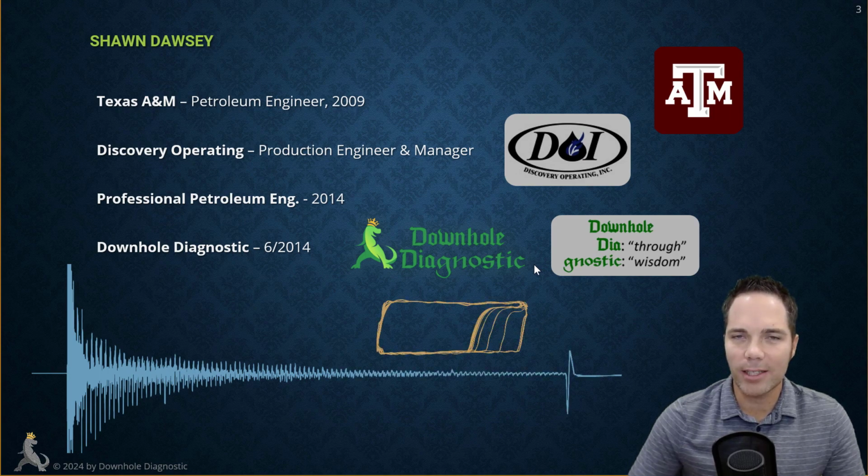We have two diagnostic tools. We have the fluid level gun that is looking down the annulus. We can see where the top of the fluid level is, if there's additional production potential, also what our bottom hole pressures are. And then our dynamometer test is looking down the rod string, and based on the shape of the downhole pump card and how the fluid load is picked up at the start of the upstroke and how the fluid load is released, we can determine what condition the pump is in, but also what condition it is operating in. And this would indicate right here that we have fluid pound due to incomplete liquid fillage.